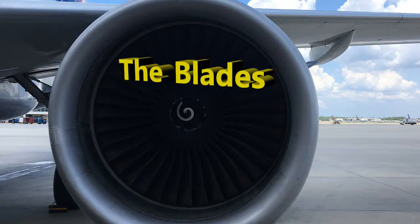Now, be aware that when you're installing, if they come in pairs, you need to keep that in mind and not separate those pairs or mix one blade with something else. The reason that's important is that when they come together as a pair, the way that you're going to install them, those two are going to be diametrically opposed on the disc.